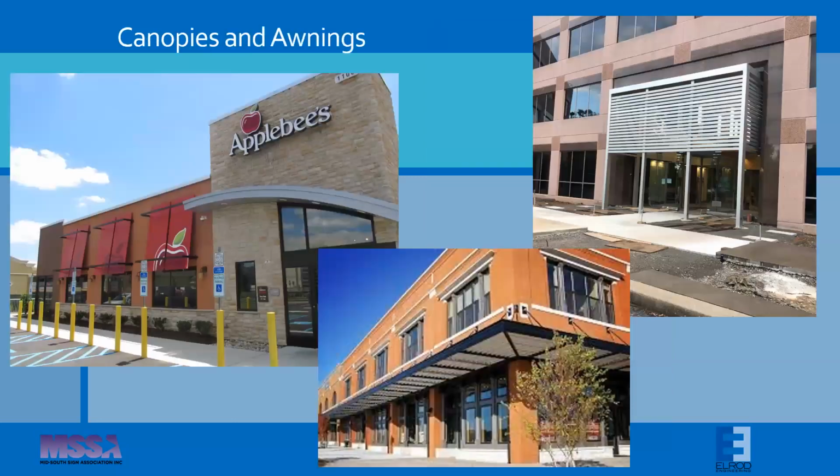Talking about canopies and awnings, I alluded to these earlier. As you can see, there can be a wide range of canopy and awning designs, most of which are relatively straightforward. However, I do like to point out the picture in the middle. When you have a deep awning like this, snow loading and drifting can become a major or the controlling issue. Don't forget, depending on your wall type, for example, if it's an EIFS wall, any bolts that hold the canopy to the wall are cantilevered out. That is, that EIFS structure is an unsupported gap between the wall and the canopy, because EIFS doesn't have any significant structural capacity. That imposes additional stresses on the connection.